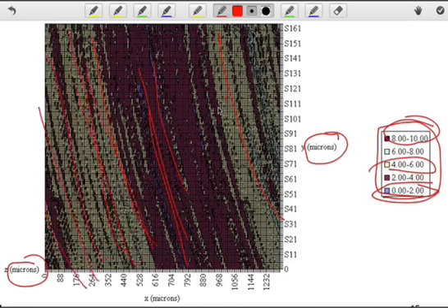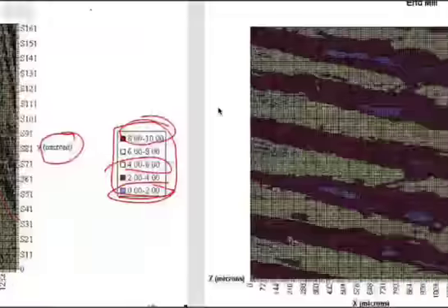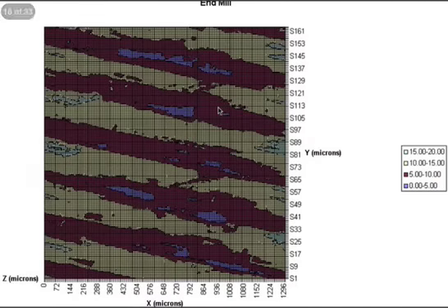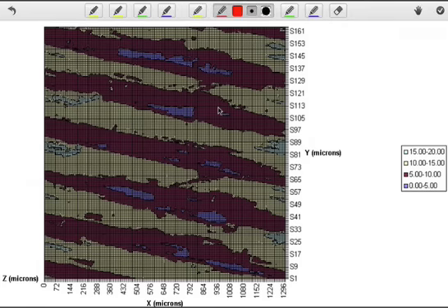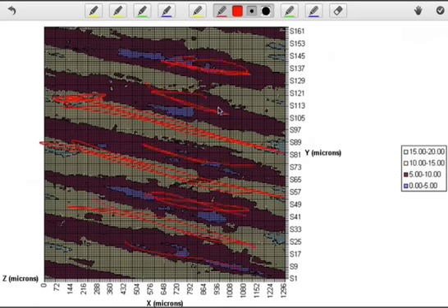So if you had a surface texture specification on this, you might want to eliminate this pattern and make it a smoother surface. Here's an example of an end mill, which you used in 248 on a number of your processes, and the lay is very pronounced here, which is not surprising based upon what you know about the geometry of the cutting tool. Again, what we have here are regions where we have high peaks followed by valleys in between. And so we see a definite lay pattern with the end mill.